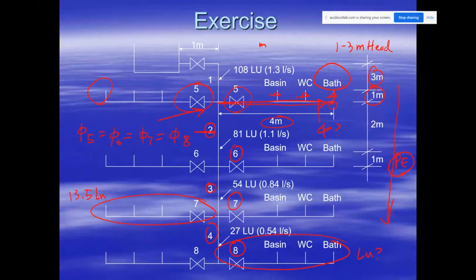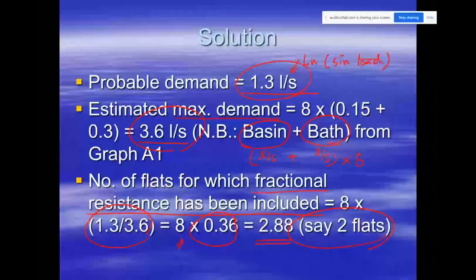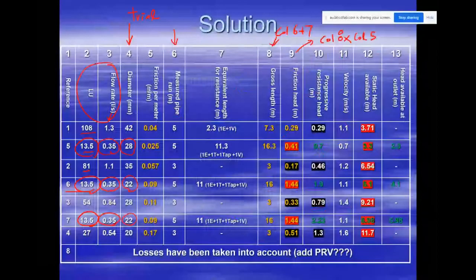Okay, so now the static head here is 3.71 at this point. Am I correct? Now 3.71, but I am concerned about what the pressure is for this point. Okay, I can't conclude. Okay, Wang Dongho asked whether the static head at that point is too large. Now for that point here, 3.71, I don't care, because this is not the real discharge pressure. I need to check the discharge pressure. Okay, how to calculate?